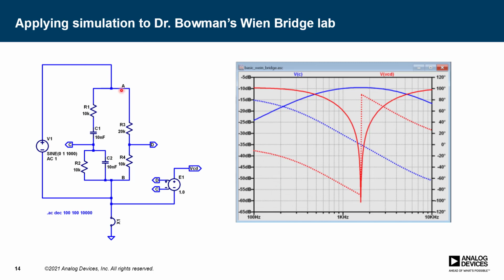We learned that whatever voltage shows up here at resonance, at my oscillation frequency, is divided by 3 and phase shifted by 2 pi radians. And so if I'm divided by 3 here, I can build myself a perfect 3-to-1 divider on the other side of this bridge. Also in LTspice, I can take a voltage-controlled voltage source and use this as the world's most perfect oscilloscope probe.